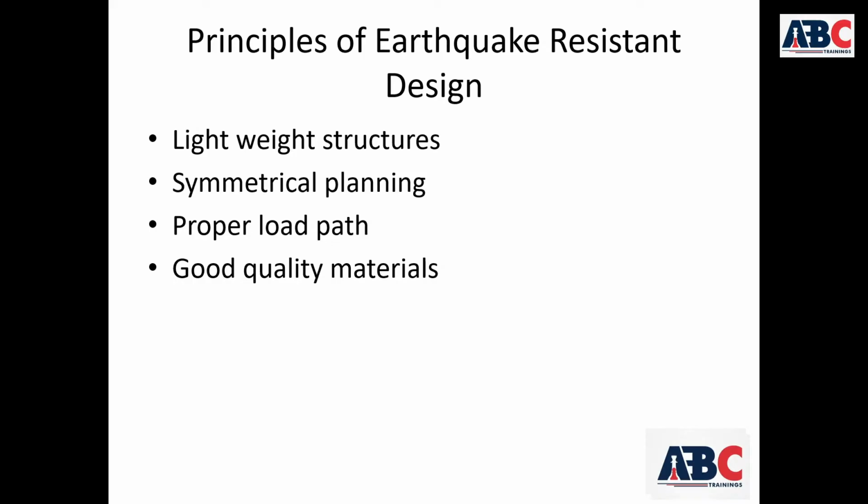Next point is symmetrical planning. Symmetrical planning plays a very important role in seismic performance. If a building is symmetrical in plan, seismic forces are distributed evenly. Irregular shapes such as L, T, and U shaped buildings can cause torsion during an earthquake. Torsion means twisting of the building.